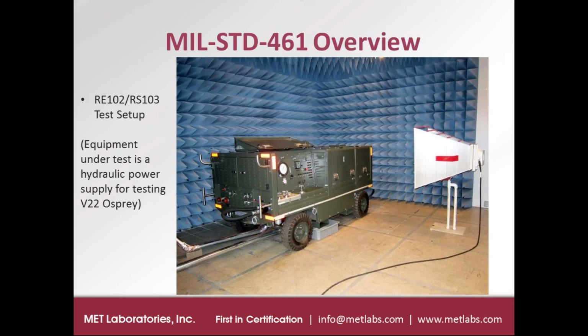And it's fairly large. For some of the test methods conducted for MIL Standard 461, the test time is directly proportional to the size of the unit, for the tests where multiple antenna positions are required. So this photograph gives an example of the antenna and EUT setup within the chamber for RE102 and RS103 testing.